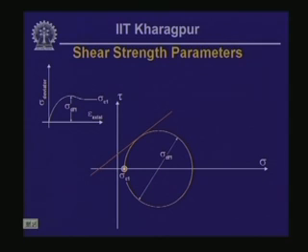If you recall, the first test of the series of triaxial tests was conducted at the smallest value of cell pressure, and the data obtained from the triaxial test, the deviatoric data, are presented on the plot near the top left of this slide, and for this data we have plotted the Mohr circle shown at the bottom right.